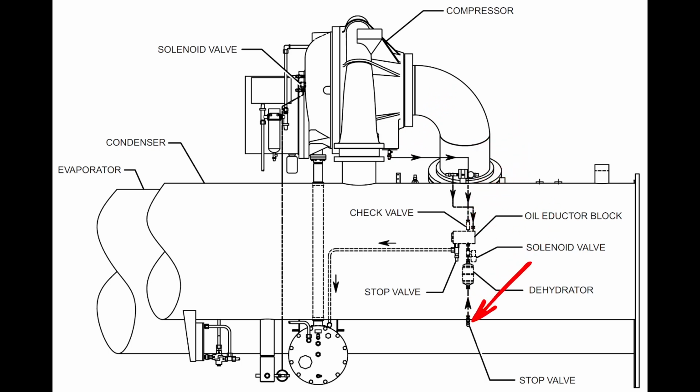That will draw off just like the CVH. And then this valve could be a little misleading. It almost looks like this is coming off of the bottom of the evaporator. This is actually, I'm sorry, coming off the bottom of the condenser. This is actually a valve on the evaporator that's about mid-level, so this one should probably be a hybrid falling film. Either way, this is your low pressure liquid refrigerant line coming off of the evaporator right here, and that's injecting into this eductor block.